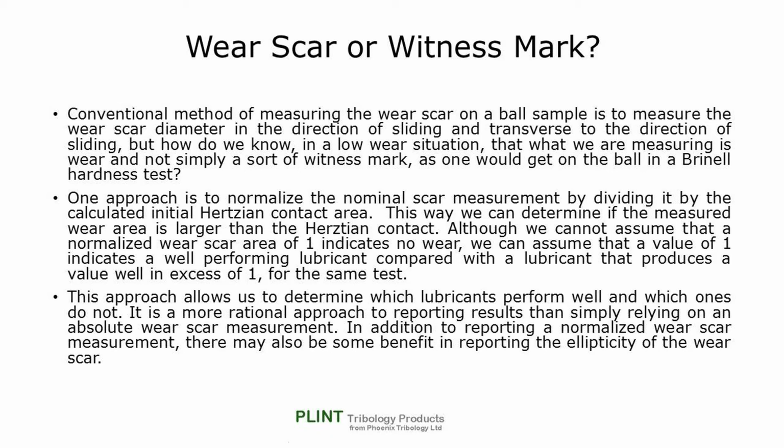Although we cannot assume that a normalized wear scar area of 1 indicates no wear, we can assume that a value of 1 indicates a well-performing lubricant compared with a lubricant that produces a value well in excess of 1 for the same test. This approach allows us quickly to determine which lubricants perform well and which ones do not. It is a more rational approach to reporting results than simply relying on an absolute wear scar measurement.